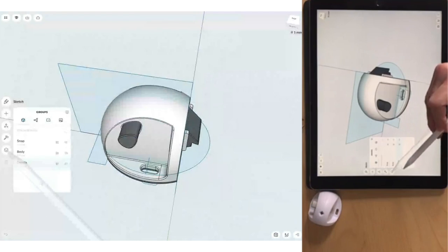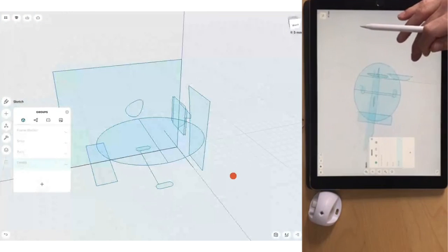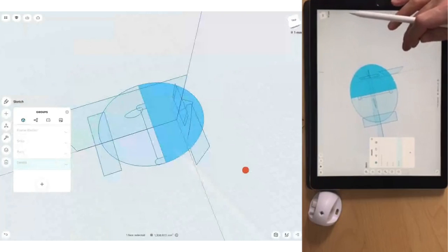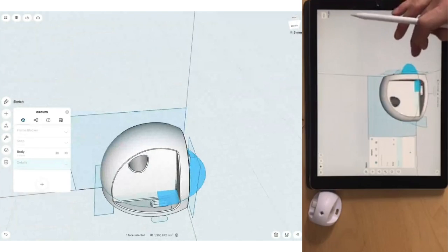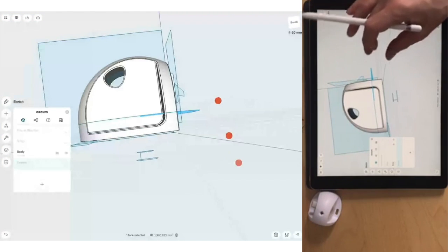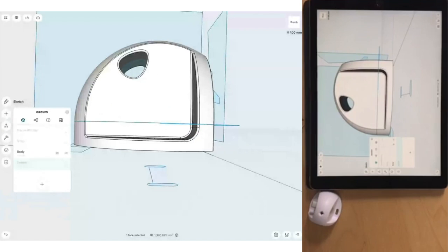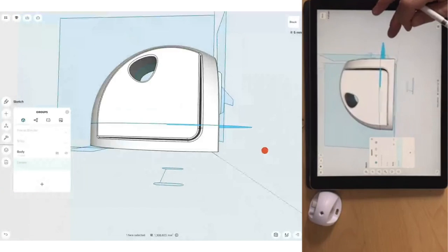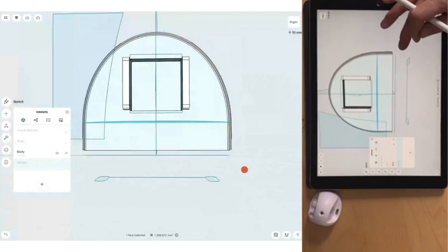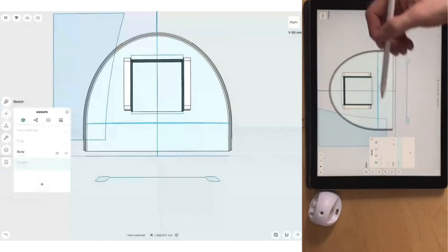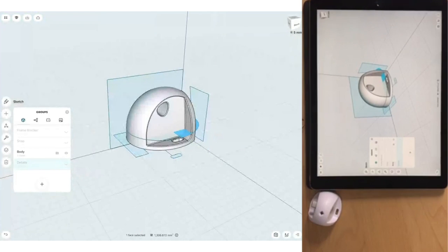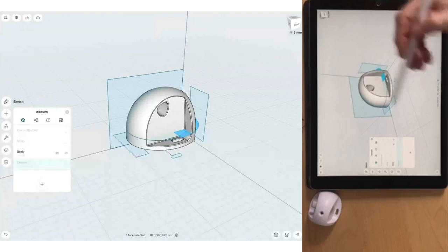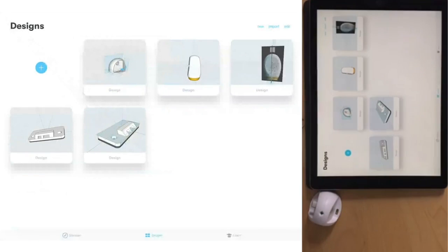So if I, for the moment, go to this, so I can show you actually the sketches first. So that is actually, as you can see, the detail. And the height of this, or the position of the revolve object is not at the bottom, it's actually on top. And then they revolve it, and then the lower part is simply extruded down. So very simple steps. I don't know, we have actually enough time to do all the details. So let's see how far we get.